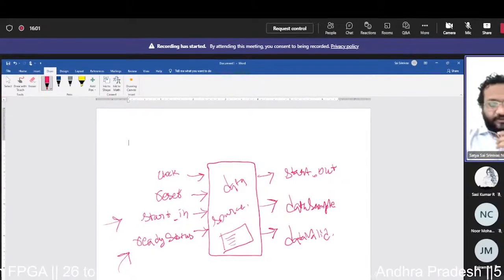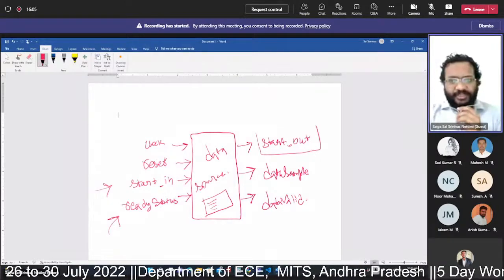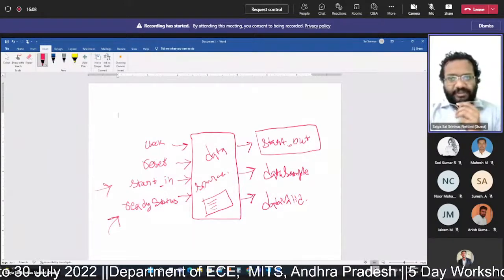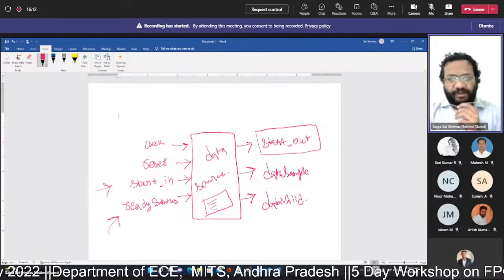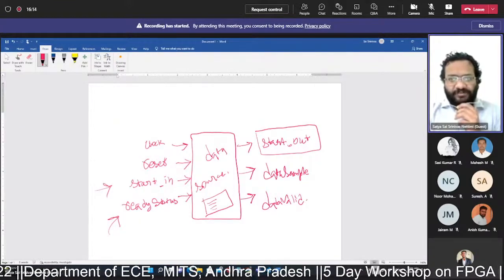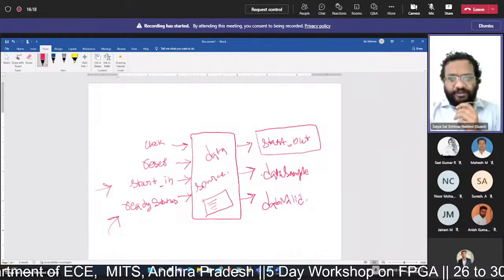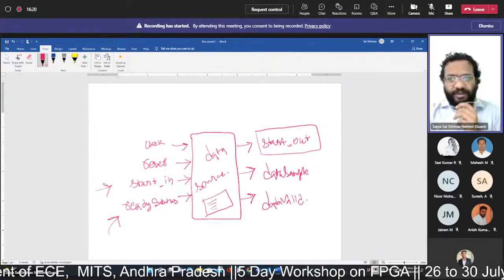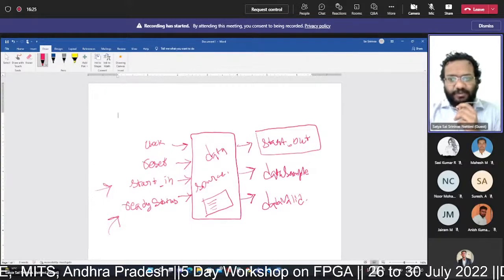Once the frame energy module is ready, the data source gives a start trigger signal to it. Once the start trigger is given, the frame energy module switches from the idle state to the computation state. Then it waits for the signal samples to arrive.